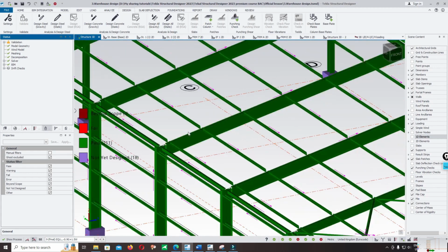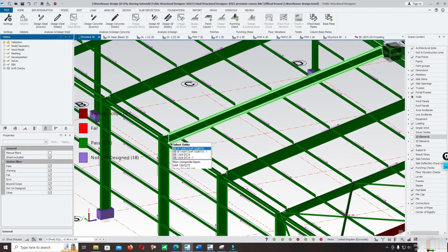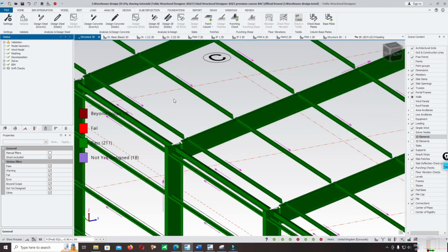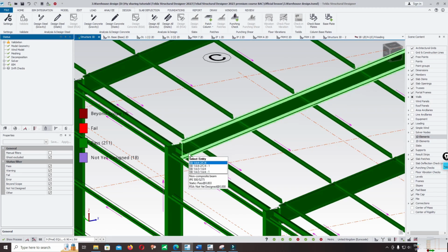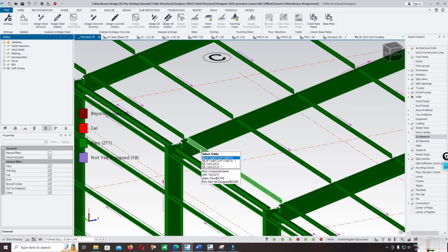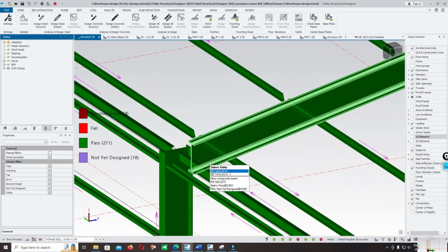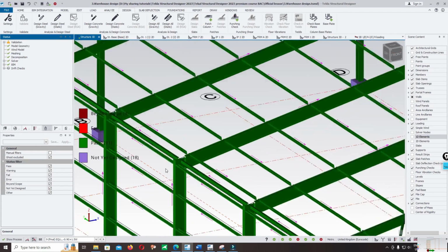So for this rafter, at the intersection with the column, the maximum tension moment is at the top, so you must add restraint to connect from the purlin into the bottom of the flange, and the other side we do the same to add restraint at the compression plane.